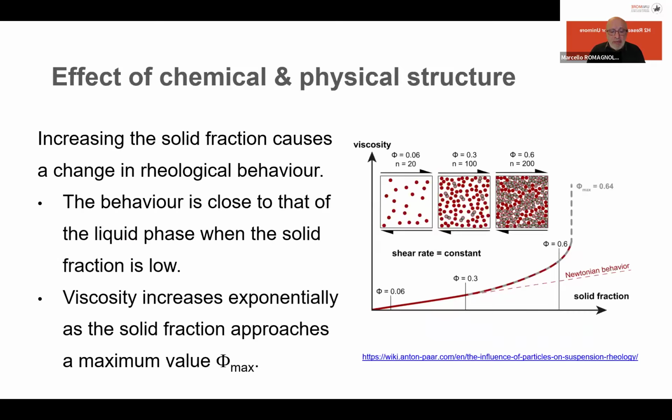Important is also the role of the solid loading. In ceramics, we are always fighting the solid fraction. In many cases, we want a high solid loading to reduce, for example, the shrinkage, and also to increase the density of the green body, or also of the body after the firing. But look at what happens to the viscosity.